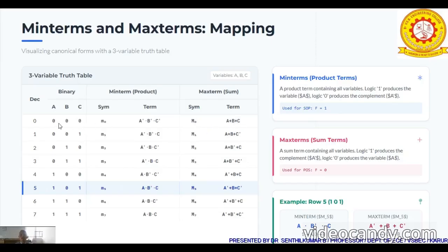Look here, unlike min term, in max term, wherever you have A with 0, it is marked as it is. When there is 1, the corresponding input is complemented. Here, if 1, the corresponding input literal is taken as it is; there it is complemented. And here it is the dot and operator, here it is the plus or operator.